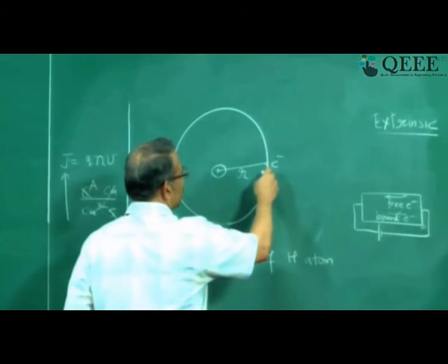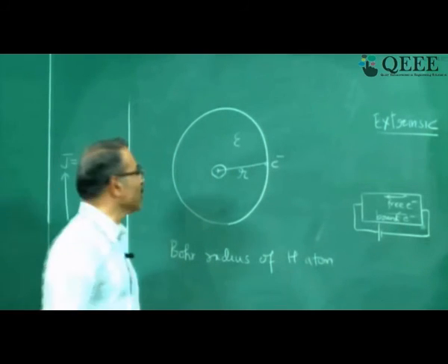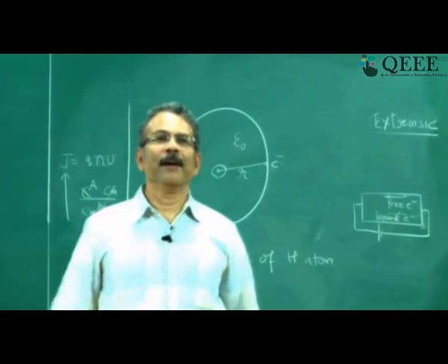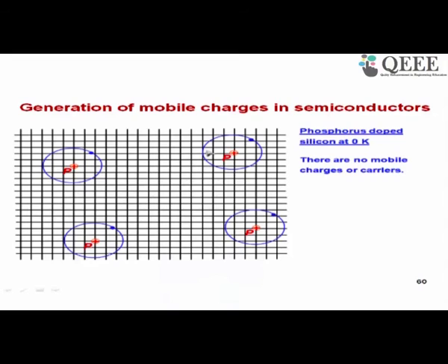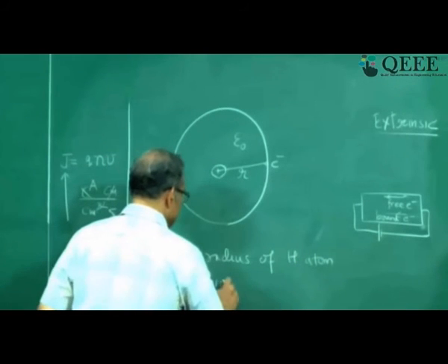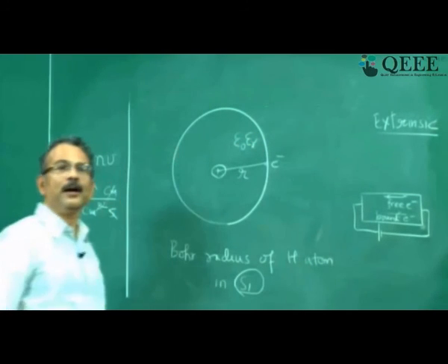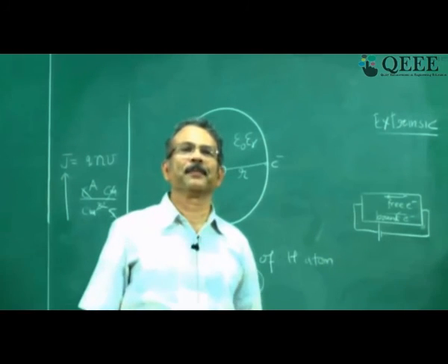then you will use the dielectric constant of the medium between the electron and the nucleus, and that will be epsilon naught, the permittivity of free space. But when you put the phosphorus atom in silicon, which is the picture here, the dielectric constant of the surrounding or environment of the phosphorus atom changes to that of silicon. So the Bohr radius of a hydrogen-like atom in silicon uses epsilon naught epsilon r. The dielectric constant of silicon should be used because a lot of silicon atoms are there.